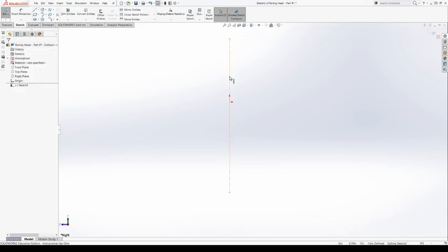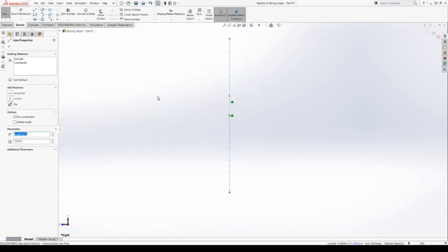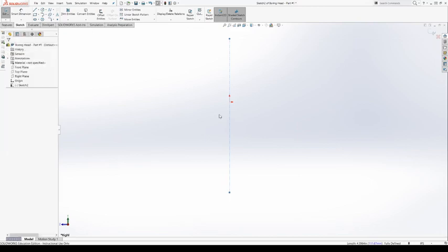The way SolidWorks deals with it is they say that this line is for construction, right? So what that means is if I do an extrusion or any sort of solid or surface creation, it won't use this line from the sketch at all. It'll just ignore it because it's for construction, right? It doesn't really matter. I could give it infinite length, but who wants that? All right, so I'm going to click OK,